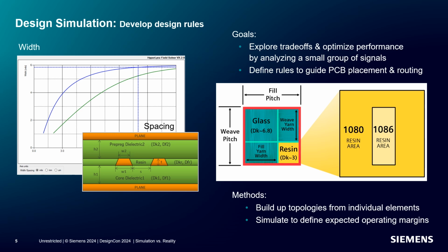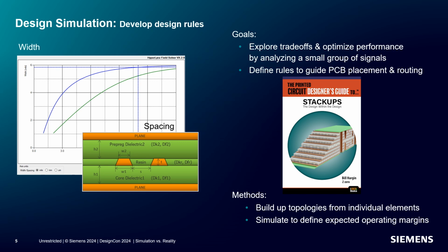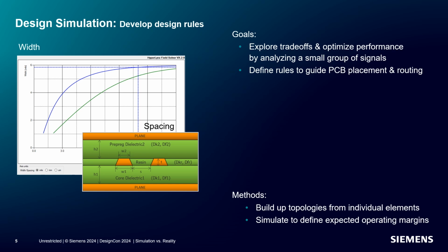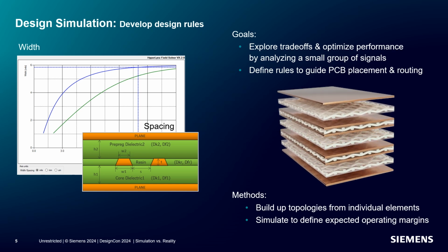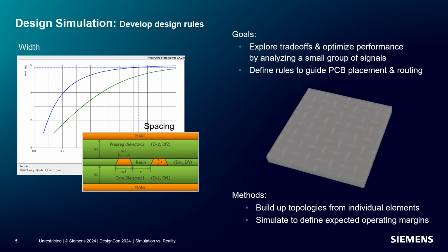There are any number of ways to mitigate this, most of which are featured in one of the chapters of the ebook which we provide, but many of the mitigation methods are material dependent. zPlanner Enterprise offers an absolutely massive dielectric library that allows you to construct very precise measurements against actual material properties. So you're building and simulating with an actual material that has a specific resin content, thickness, weave area, DK, DF values, a specific TG value, specific type of copper etch, etc. If you are developing your design rules without this information in place, how accurate are those rules? And at what point will they have to change?